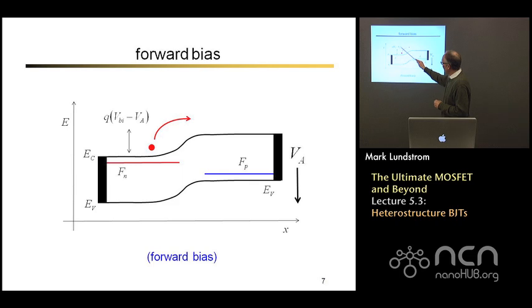We've lowered the barrier height, so we've enhanced that probability exponentially. That means that the density of electrons on the P side, right at the top of that barrier, is what it was in equilibrium. That's what I've denoted as n_p0 here. That's just n_i squared divided by the doping density on the P side. But it's exponentially enhanced by e to the q V forward bias over kT.